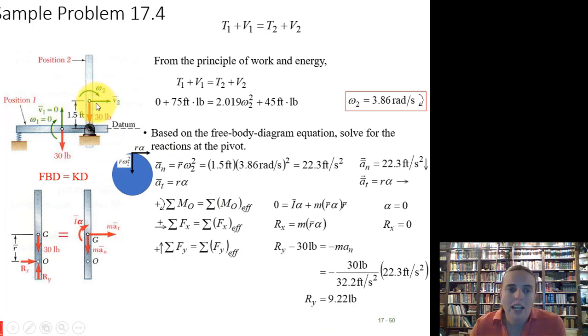It's caused by the velocity that's happening up here. So because of that velocity, you have r omega squared or v squared over r, which means that the reaction is not equal and opposite to the weight anymore. So that's a good mixture of energy balance, looking at energy versus work and energy, how those are the same things, and also mixing that in with a force balance as well.